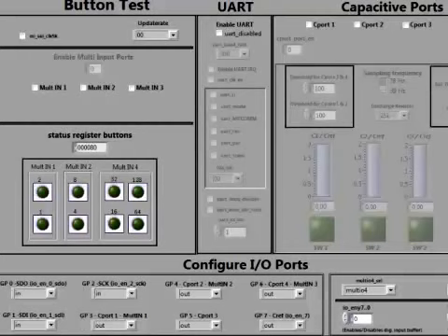To configure a multi-input pin, first enable the multi-input pin, then configure the pin as input, next ensure that the digital input buffer on that pin is switched off.